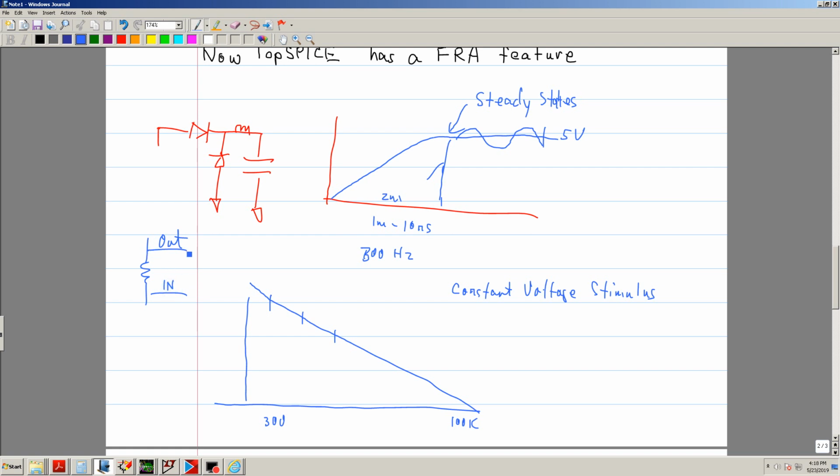Remember, you're injecting a sinusoidal signal across your injection transformer or points, and you're supposed to get a nice sine wave on both sides. But if you inject too much signal, you might get a sawtooth looking signal. In that case, you might have too much signal.